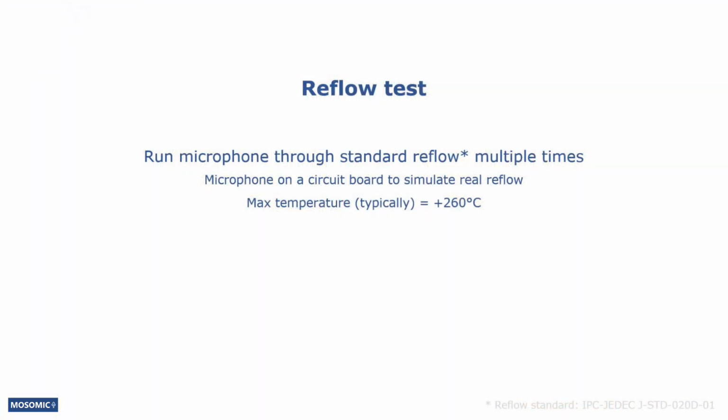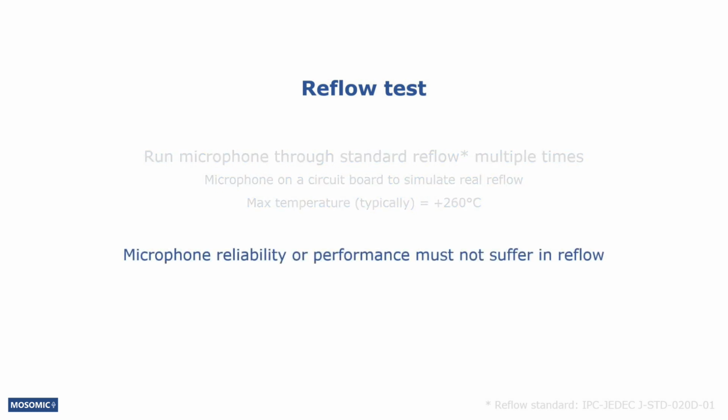A surface-mounted component must naturally be reliable in reflow conditions, even if it goes through the process multiple times. Reflow tests are done simply by running the microphone on a circuit board through a standard reflow process multiple times. The maximum temperature in the test, just like in a typical standard reflow, is 260 degrees Celsius. This test is done simply to make sure that the microphone, including the package and the semiconductors in it, can handle multiple reflow rounds without an impact to performance or reliability.